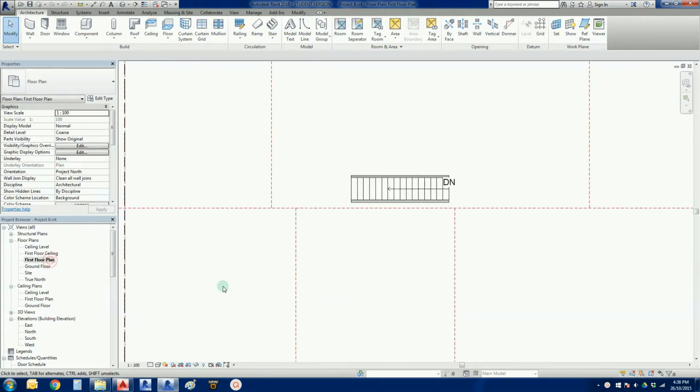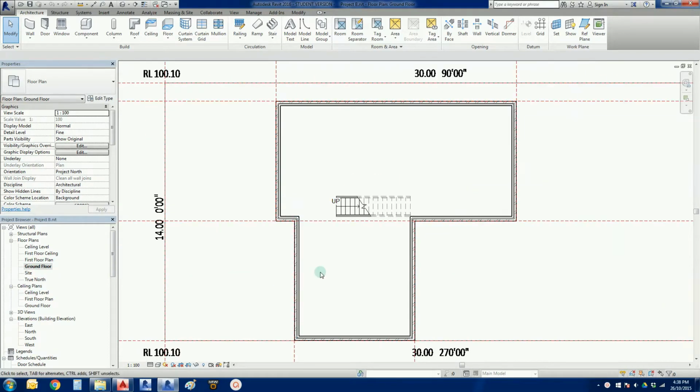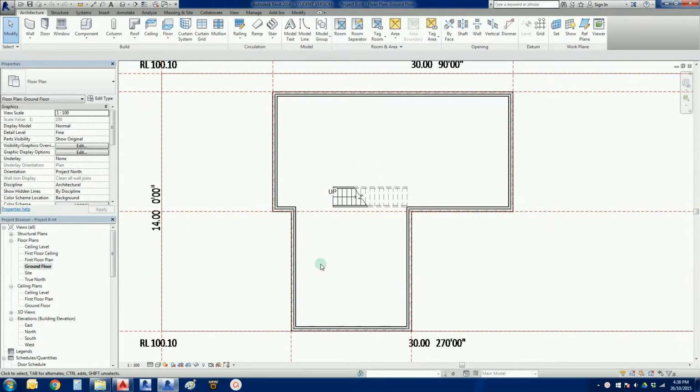So what we want to do now is go to the upper floor, and you want to punch up some fresh walls up the top, but before we do it we need to create a new type of wall, because I want to create a weatherboard effect wall, and Revit doesn't have one, so I need to make something.